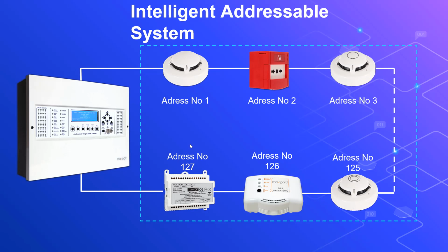Following the risk analysis, needs identification, and emergency scenarios, the fire alarm system should be designed. In such structures, fire detection alarm systems go beyond being just a system that detects fire early. It becomes crucial in interacting with the mechanical and electrical systems used in combating the fire. In this case, the system type must be addressable, meaning it should provide precision point notification.